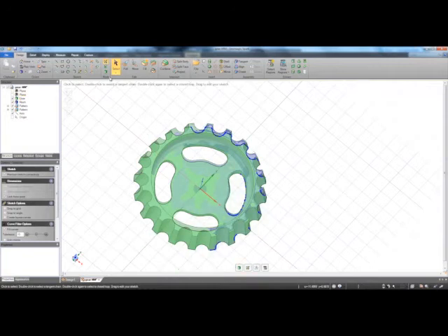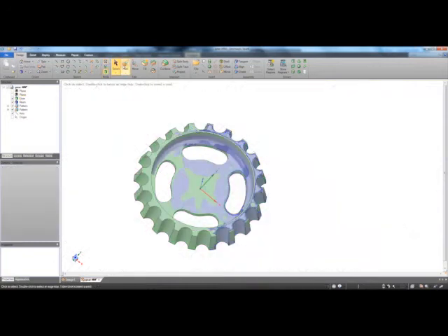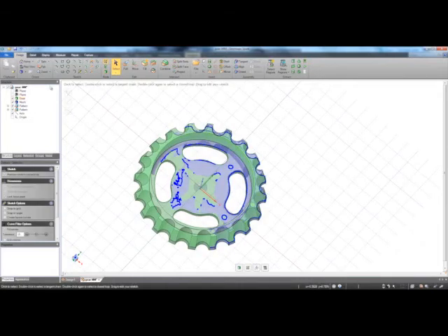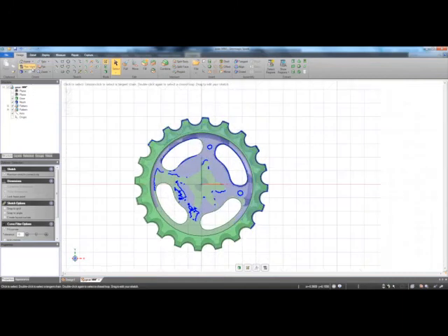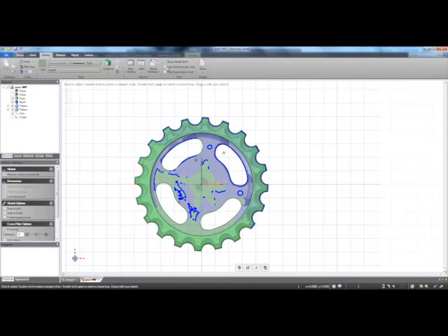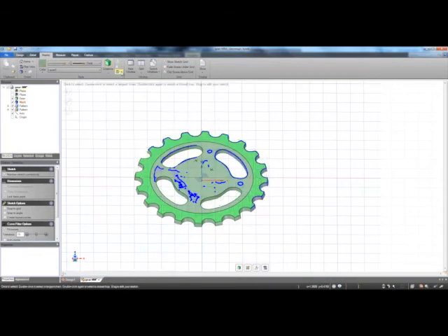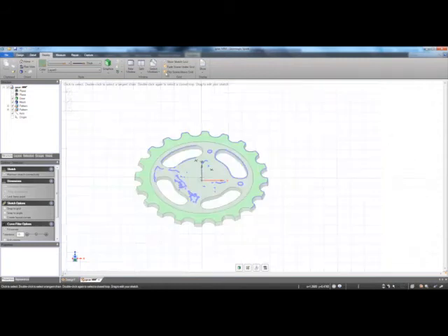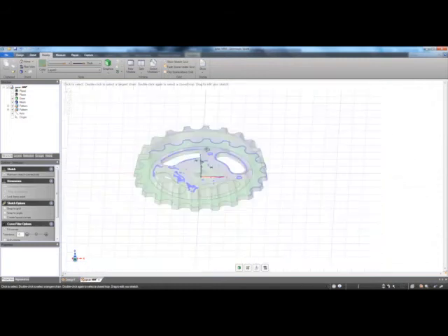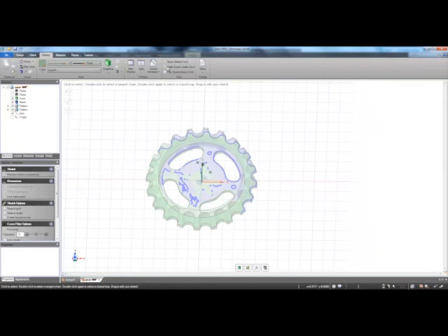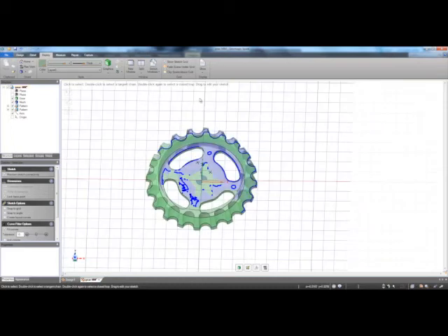So go into sketch mode and actually go back to 3D and show you guys again. So make sure you're in select mode, go to sketch, and you'll see I'm going to select on that face. Then I can go over to plan view, and that squares everything up. And there are some settings for display mode while you're in sketching. So if you go to display tab, I can turn on the ability to clip above the grid, fade below it, not clip. So you'll see they're just different display settings that are just check marks depending on what you like on your end. So I'll go ahead and turn that off.